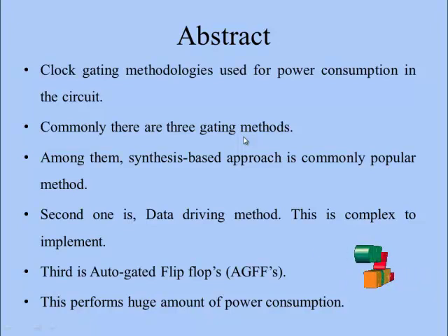So, a low-power flip-flop design featuring an explicit pulse-triggering structure and a modified triggering, single-phase clock latch based on the signal feed-through scheme is presented. The presented design successfully solves the long discharging path problem, and it also reduces the power consumption.